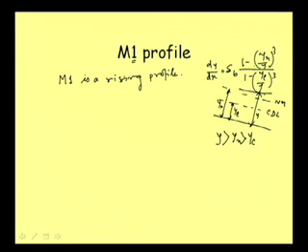So numerator and denominator both are positive, and when it is mild slope, the bed slope is also positive. We talk about negative bed slope only when we talk about adverse slope. Slope falling in the direction of flow we refer to as positive slope.